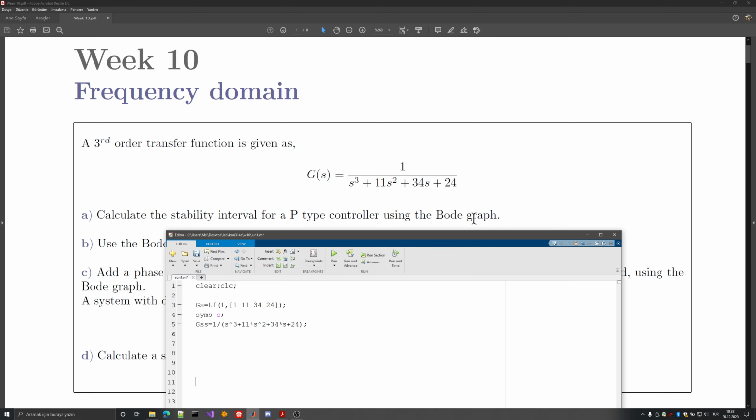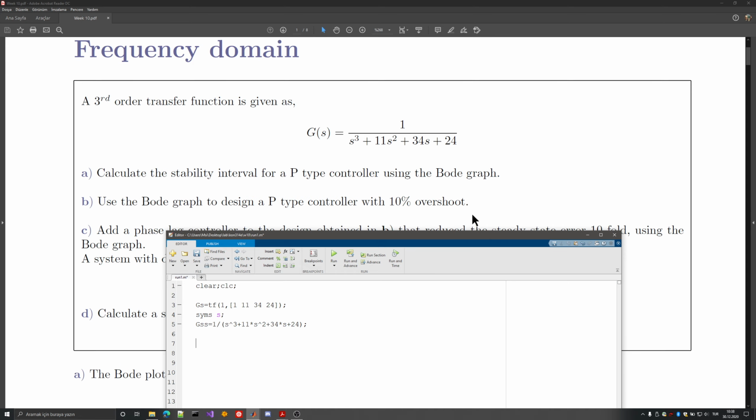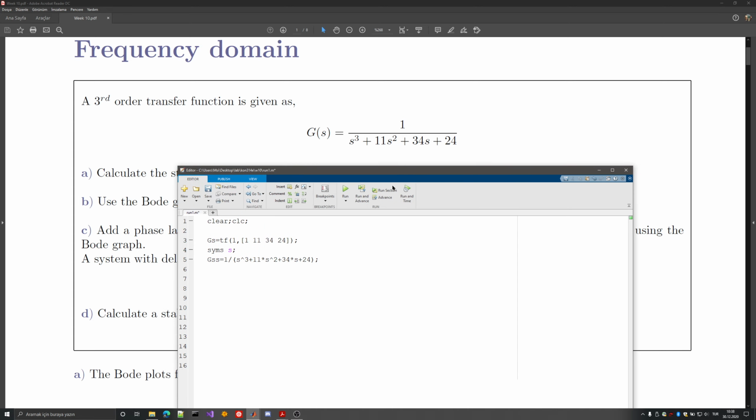Okay. So I've told you that you can just go ahead and plug in s equals j omega. Let's do that. Let's define omega, which is a real number, and remember that you can tell the symbolic engine that this is a real valued variable. It will get rid of the conjugate because that's not necessary. It's equal to itself if it's real. So let's say j omega, and we will use subs, and instead of the value s, we will have omega times 1i.